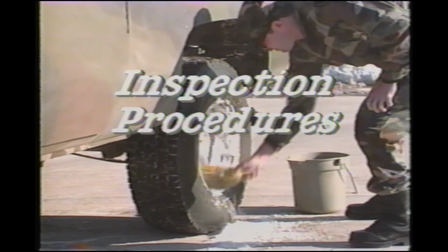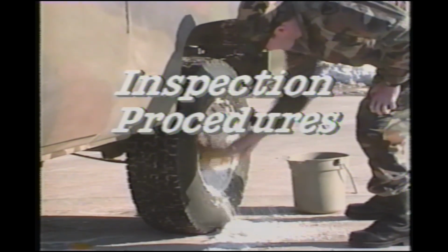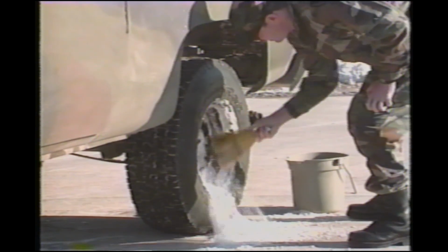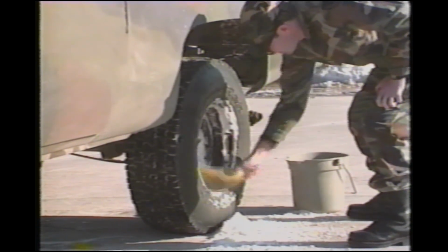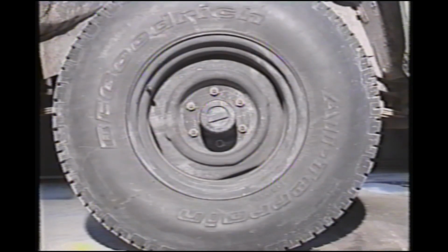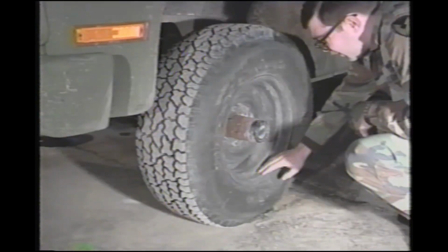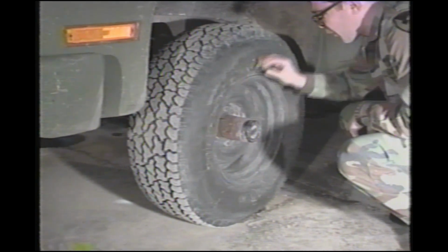In order to perform a first-class tire inspection, the tire must be clean. Wash and scrape any mud or snow from the tire. Use a systematic approach on each tire. Begin at the hub and work around the tire to the inside rim. Perform your inspection one wheel at a time.